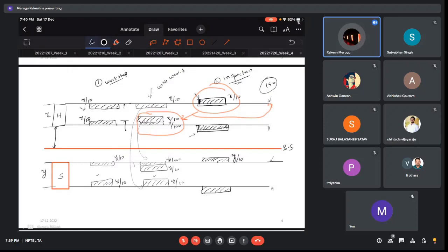So it is like something in between the inspection and the workshop gauges. Still I have some rejection, some parts which are not within the limits, and still I have products which are within the limits, but I am rejecting them. But compared to workshop and inspection, these ISO gauges will accept most of the products which are within the range, and some we have to reject. That is the term we coined as necessary evil in metrology.